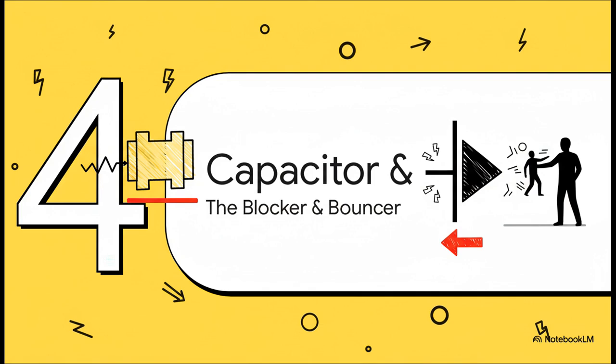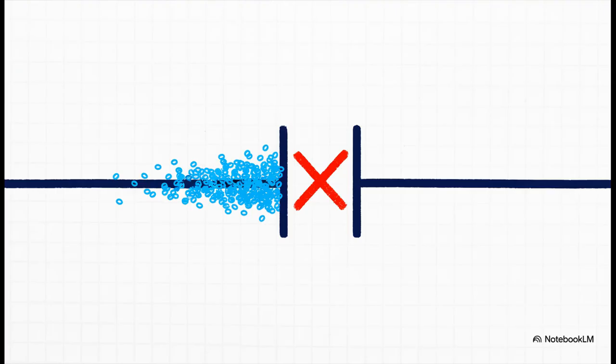If the resistor is our predictable workhorse, think of the capacitor as a total roadblock. And the diode, well, the diode is like a really strict bouncer at a club. First, the capacitor. Now this thing does some really cool stuff when current is changing, but in a steady DC circuit, its job is dead simple. After a tiny little moment where it charges up, it basically just acts like a permanent break in the wire. It completely stops the flow.